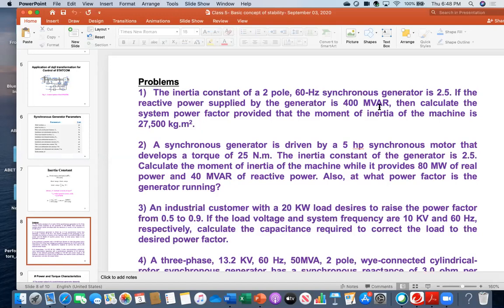Lakshmi, did you calculate the P value, real power? How much was that? Yes, Dr. Ali, it's 781.2362. No, that is the MVA value, the S value. I am talking about the P value, capital P in the power triangle, the real power value in megawatt. To know that, you have to find S equals root over P square plus Q square.